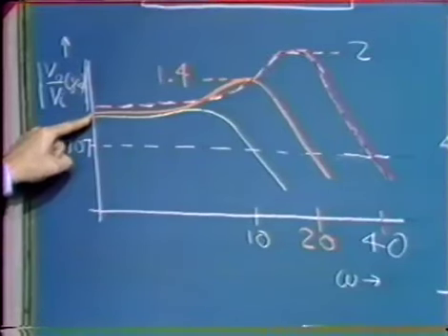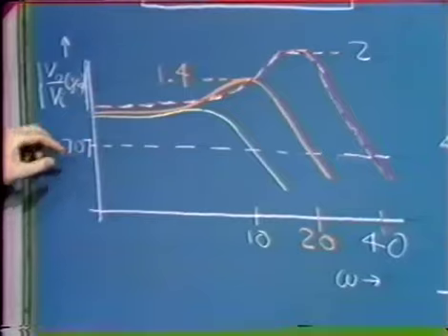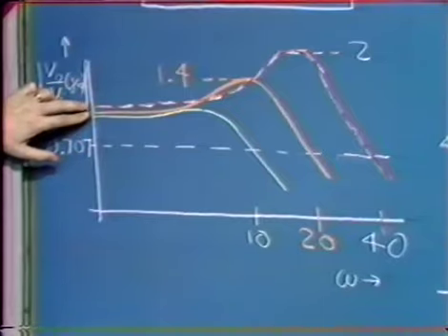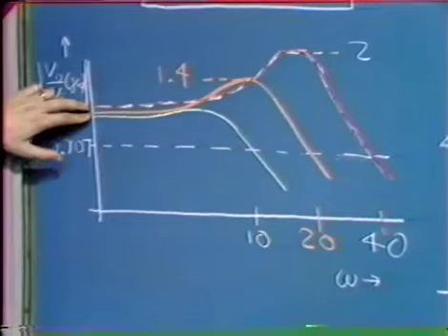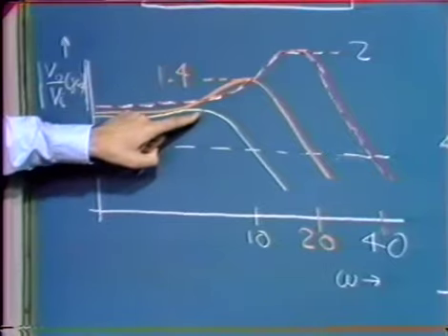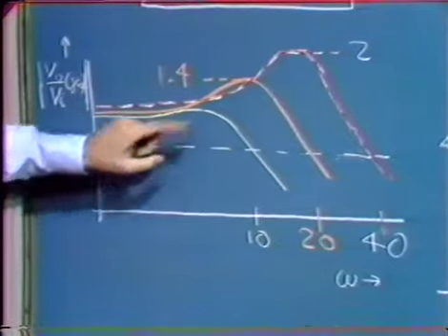In the case that we worked out on the Nichols chart a little bit earlier, for all three of our systems we had very nearly a magnitude of the closed loop gain of 1 at sufficiently low frequencies. And so the peak values here very nearly reflect M sub p.